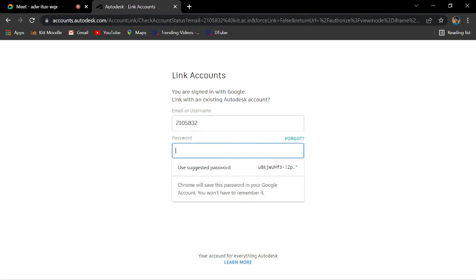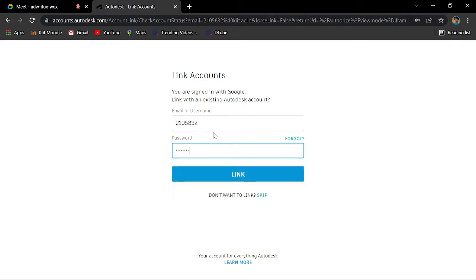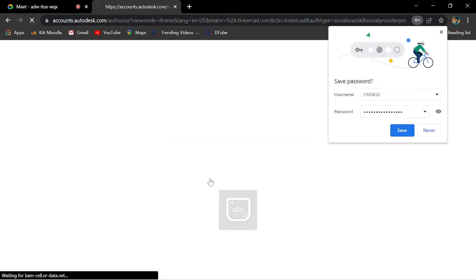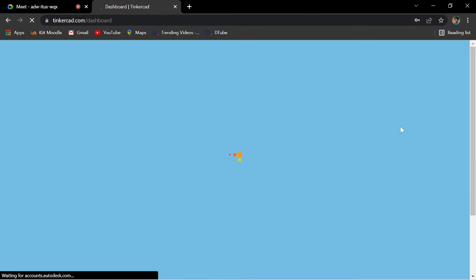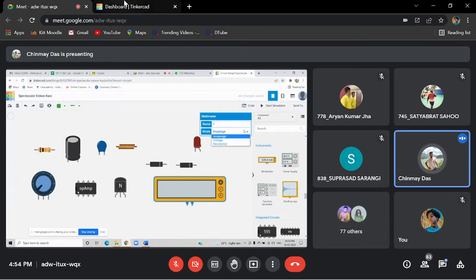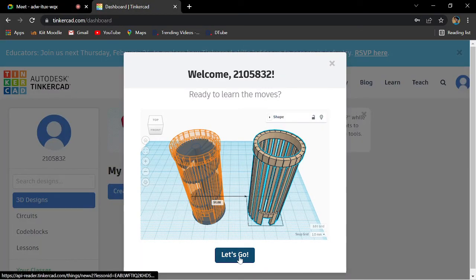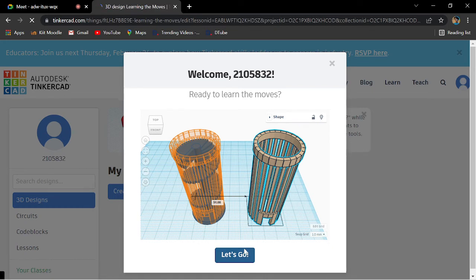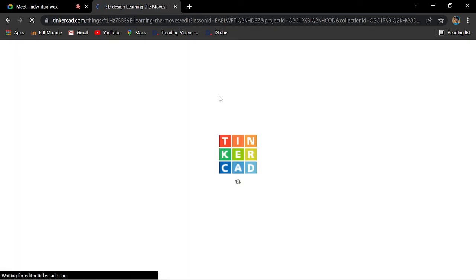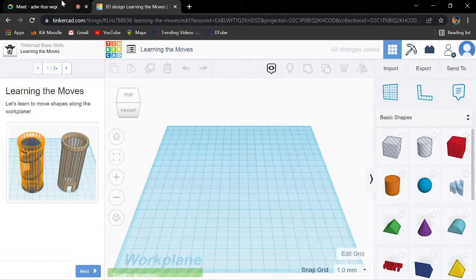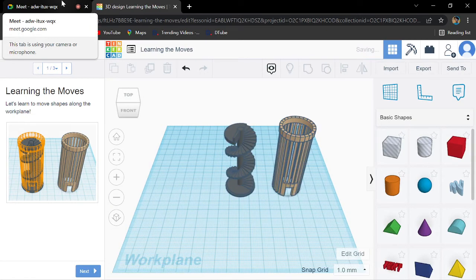If you click on this, okay, the name you can change, and the mode. If you change it to amperage mode, that means now it's an ammeter only, and you have to connect it in the circuit in series. Okay. Similarly, you can change it to voltage by selecting voltage. Now it can be used as a voltmeter. Okay, and by selecting resistance, now it can be used as an ohm meter. Okay,